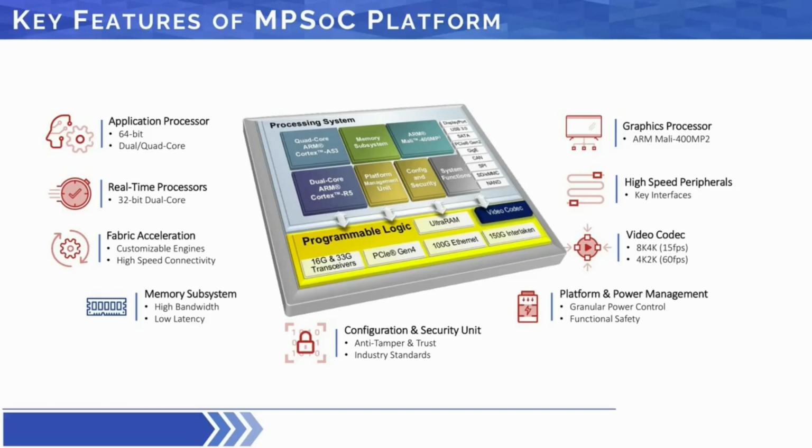The peripherals are extended through the hardening of a transceiver block in the processing system itself. And this enables interfaces like USB 3.0, PCIe Gen 2, and a native DisplayPort. And with this MPSoC built with many elements which you naturally need, you will not need all of them. So the power management provision is enhanced and increased granularly to turn on blocks as and when required.